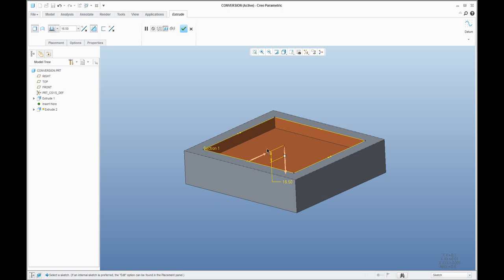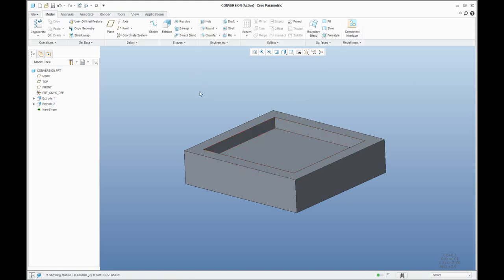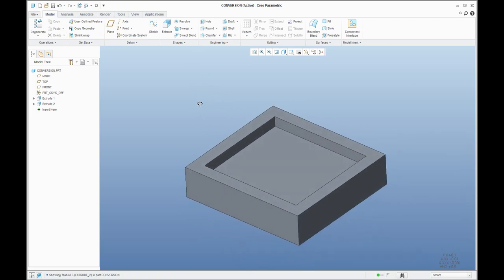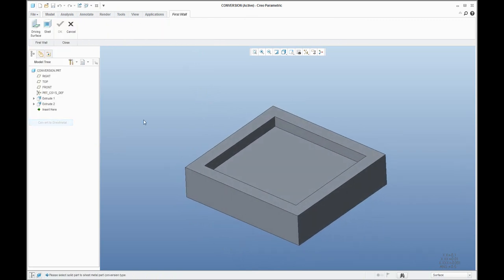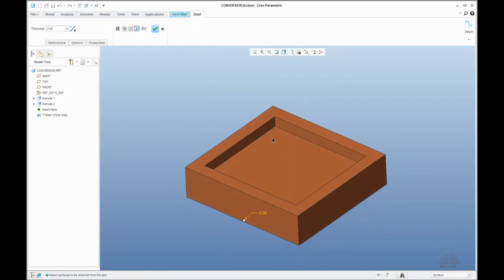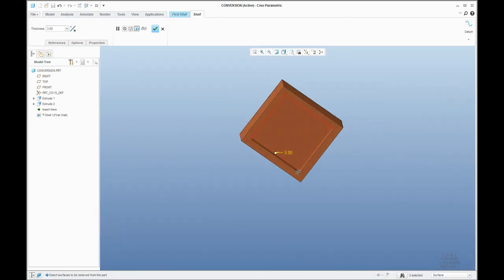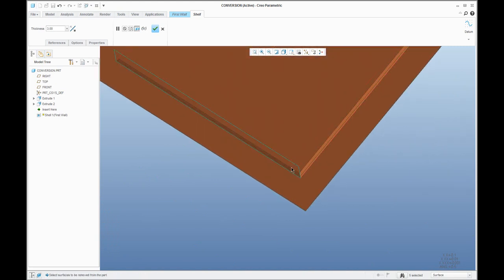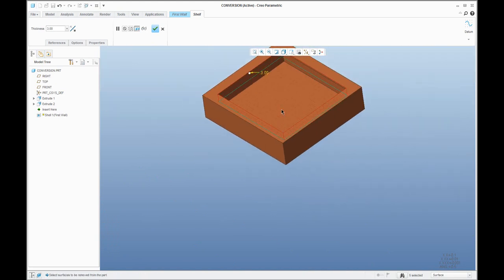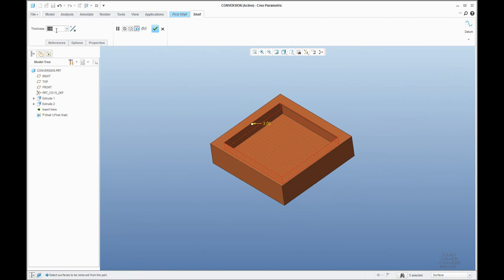Specify the depth. You don't care if it is 1 or 2 millimeters, you need to only go down and set the minus value. So if I select the minus value, I have prepared the shape that I need to show you, and again I will go back to convert to sheet metal. So I will select the shell and I will remove all inner surfaces. What the system will create for me, you will see, I will change it a little bit.